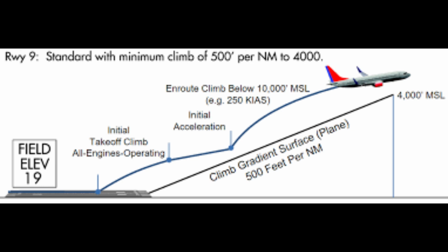On international flights, pilots must be prepared to differentiate, if necessary, between barometric pressure equivalents with inches of mercury and millibars or hectopascals to eliminate any potential for error. For example, 996 millibars erroneously being set as 29.96. For a typical IFR flight, the majority of in-flight time often is flown in level flight at cruising altitude from top of climb, TOC, to top of descent, TOD.